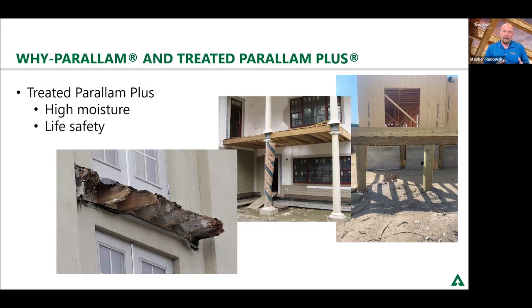You mentioned the life safety aspect of this product. Is there any fire resistant version of it that's available, or can it be made fire retardant? As of right now, no, it cannot be made fire retardant. The fire resistance that's going to be in there would be similar to any type of solid member in its burn rating. That's going to be something that I would have to go back and look up. I know somebody posted up there, is there any fire I-joist that's out there? And right now, no, we currently do not have a fire resistant or fire rated I-joist.